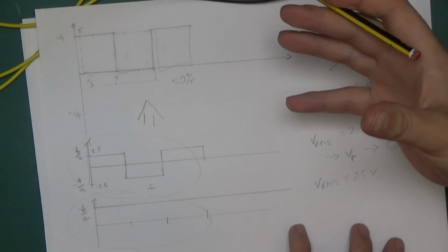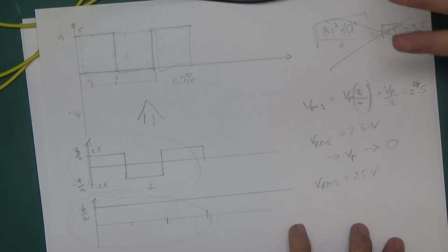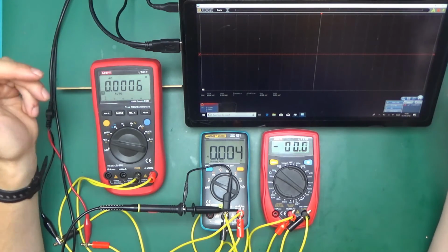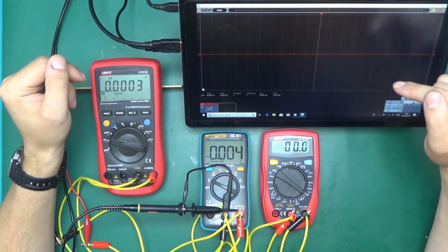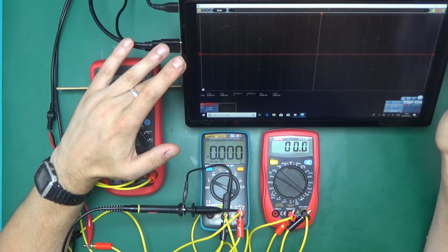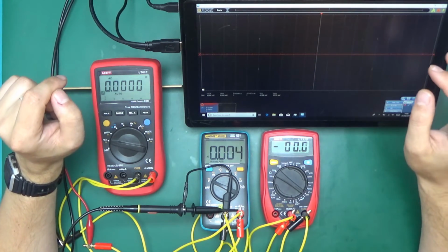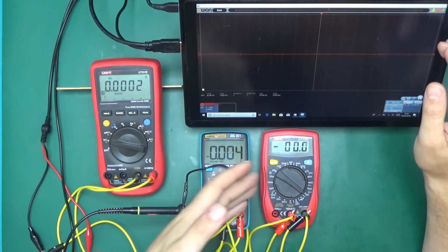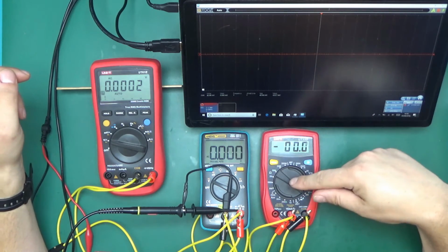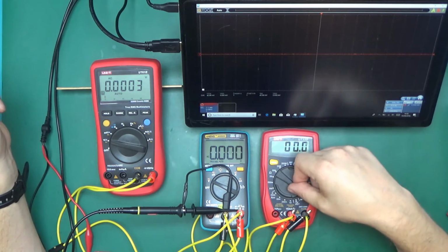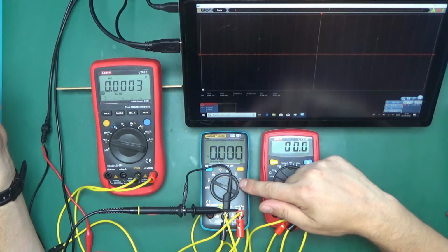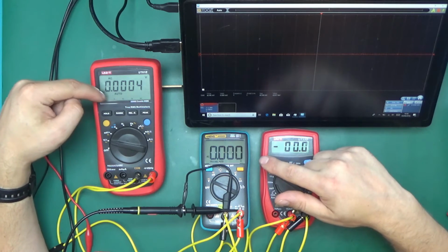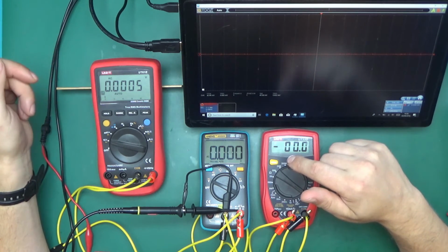Now we can get the interesting bits out of the way. We can have a look at what the multimeters will show and whether they actually are true RMS or maybe not. So let's make some measurements. To do that, I've prepared this little setup with the tablet interface for the ON 1022i oscilloscope, the FY3200S signal generator, and that is connected to three multimeters. As you can see over here, we have the UT33D, the basic multimeter, non-true RMS. Then we have the Aneng AN8002, supposedly true RMS, and the Uni-T UT61E, again supposedly a true RMS multimeter, that's what it claims.